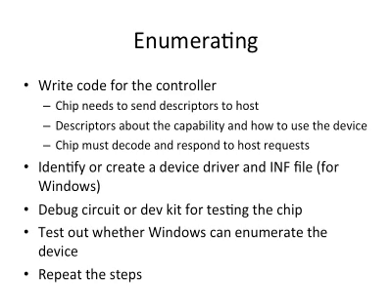You may need a debug circuit or development kit for testing the chip, and you want to test whether Windows can enumerate the device. And you want to repeat the steps if you have multiple endpoints present on the device.